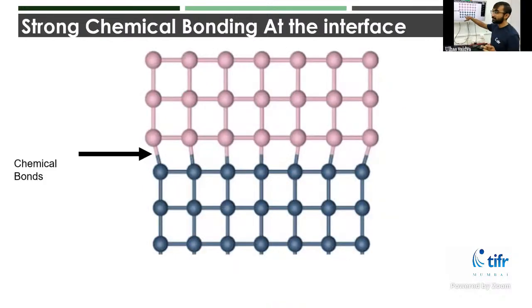First of all, you have the substrate. And if you try to grow on the substrate directly, what will happen is it will form a chemical bond. And these are strong covalent, ionic bonds. So you won't be able to peel it off. So you need to devise a strategy such that the material you are interested in, you will be able to peel off. But you also want to make sure that it grows in a high quality single crystal manner. So how do you do it? And the answer is using a material that I alluded to, which is graphene.